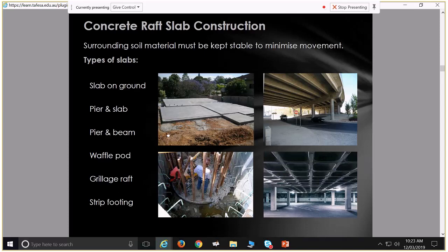Could you use that if, say, one third or one section of it seemed like the soil is completely weakened, so you put a pier underneath that section of the slab, like the rest of it? Yeah, exactly. That is where you see it getting used a lot. As I think I mentioned last week, we're looking at northwest of Adelaide, from Bowden, Brompton through toward Port Adelaide. You've got pockets in there where they excavated for clay.